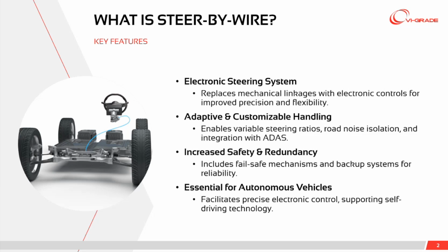Such a system provides adaptive and customized handling, thanks to the fact that a variable steering ratio can be applied. Road noise isolation is guaranteed by the absence of a mechanical linkage between the steering wheel and the steering system. And the integration with ADAS is straightforward.